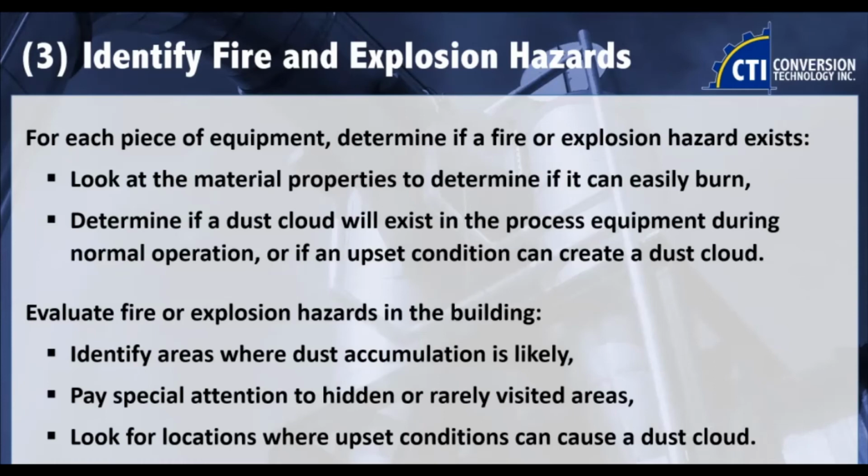Once you've gotten your equipment, you now need to identify the fire and explosion hazards. So you know the equipment, you go through that equipment and areas, I repeat, and areas, and you look at what can burn, how it can burn, how can a dust cloud exist in this equipment or area during normal operation, or would it only happen during an upset condition?